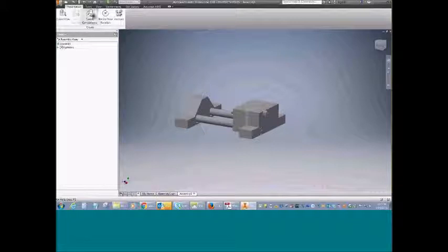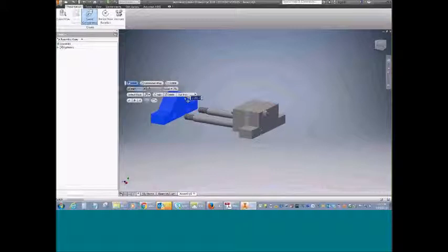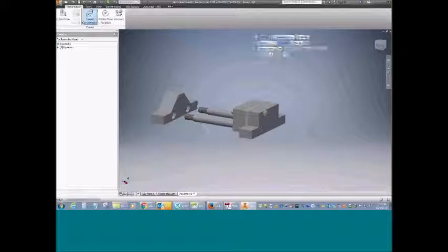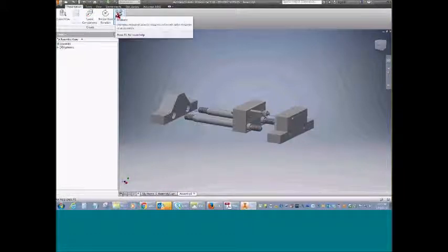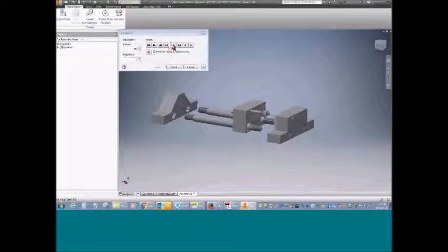So real quick here, this is the exploded assembly. It's just a different file. So we bring in our assembly and then start pulling that apart. Can specify distances and all that great stuff, and start bringing parts out. And so we'll go through this, and it's really pretty simple. There's one tweak components, and then you can animate that, so you can show it going together, kind of the way you took it apart.